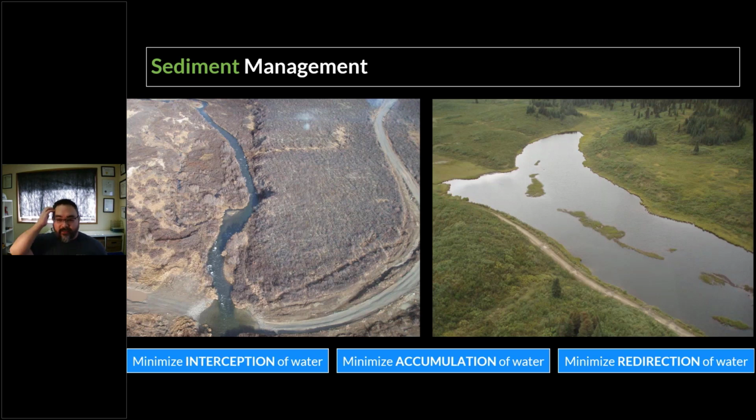And you can do things like narrowing the road in areas of sensitivity so you reduce your cut. And then you can reduce that more by taking the ditch out and insloping the road, and then dealing with that water through insloping and road grade, and getting it somewhere where you feel comfortable, where you have more room to get that water across. By taking out the ditch and narrowing the road, you're greatly reducing the ground that you've exposed.